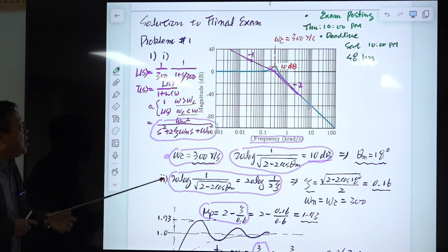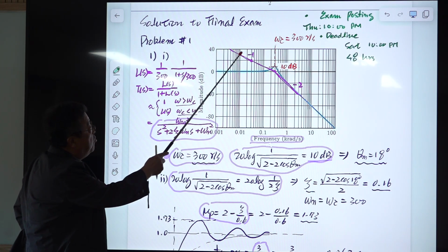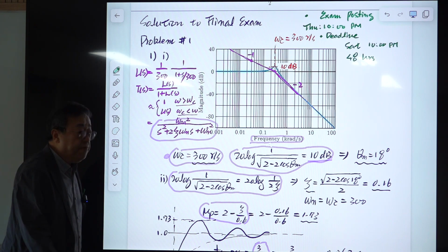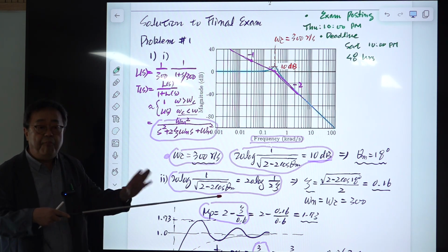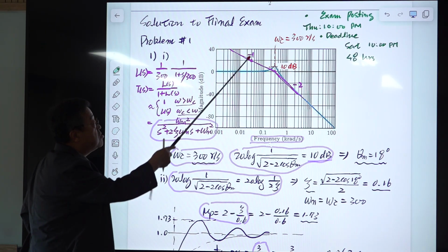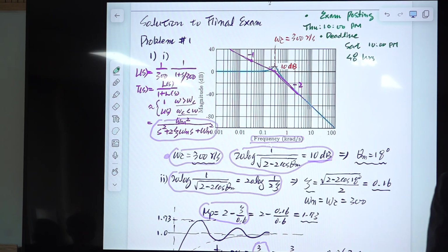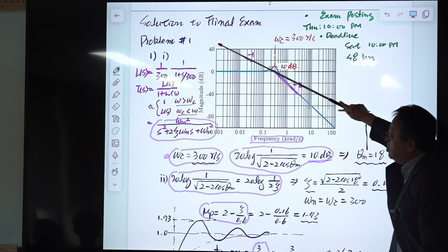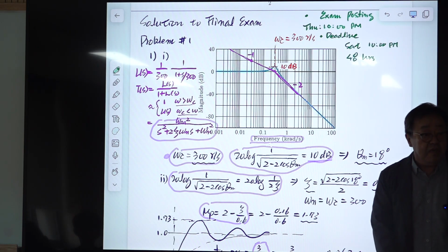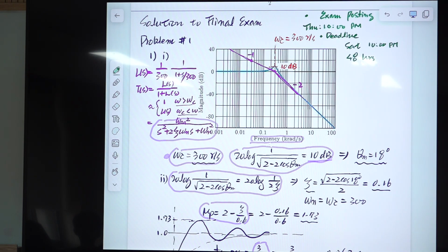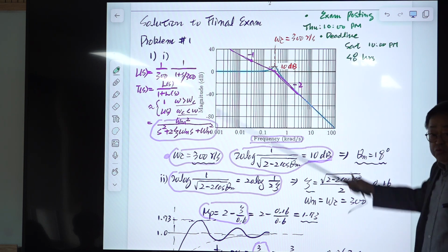And we assume that this has this -1 integration structure. If the plant is very complicated and you need poles and zeros, many poles, 2 poles, 2 zeros, or something like that, and an integrator, assume that using proper compensation it is shaped in this manner. That is always possible, right? If there is no integrator, you add the integrator in the compensation. If there are poles and zeros, something strange in between, you try to cancel them. To make the loop gain this shape is called loop gain shaping.